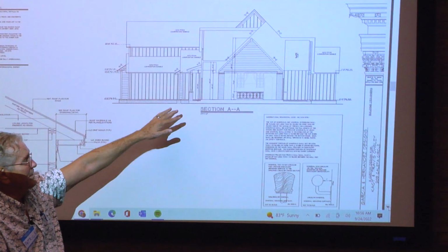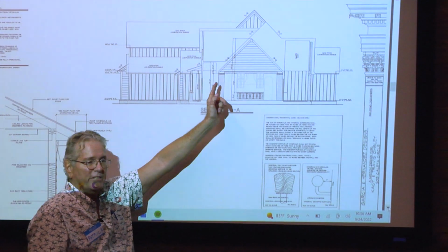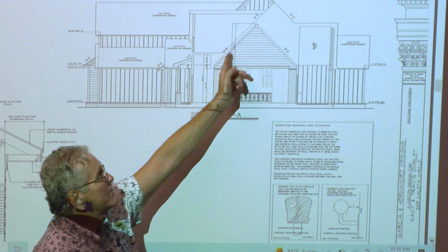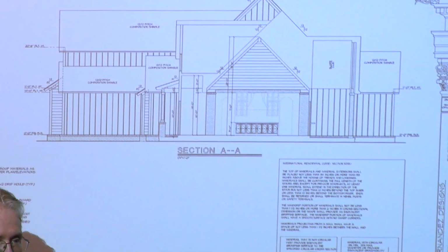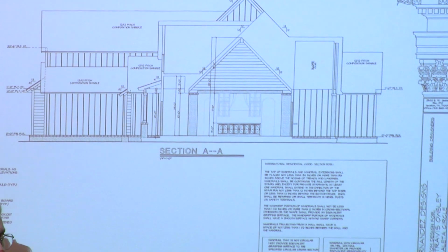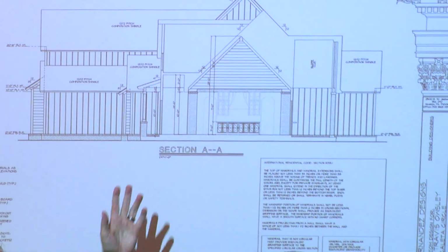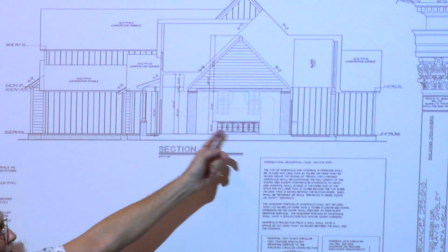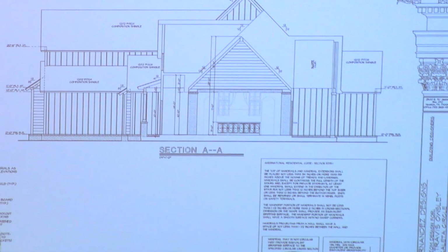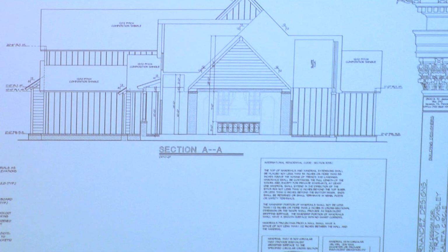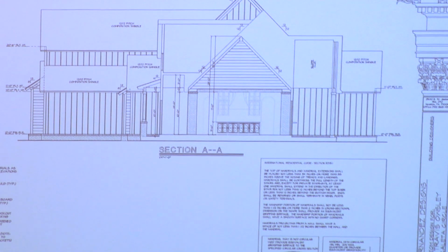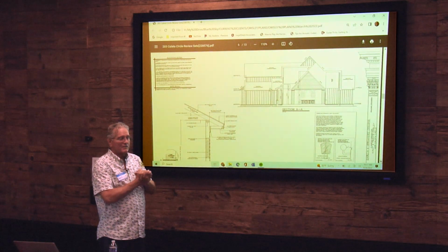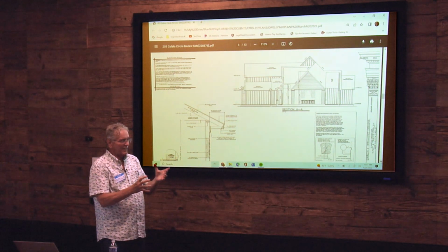So he had this because inside their living room, their family room, is this vaulted ceiling, which goes underneath the ceiling of the roof itself. So there's two structures framed there. You can't even get that perspective until you have a cross-section to look at. If your house has lots of cathedral ceilings, or cath ceilings as they like to say, ask for some cross-sections, because the cross-sections will bring everything together for the framer.